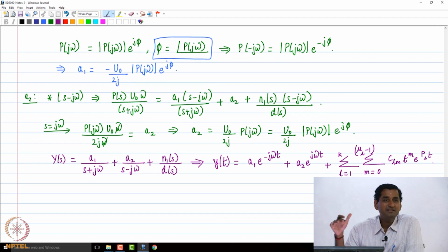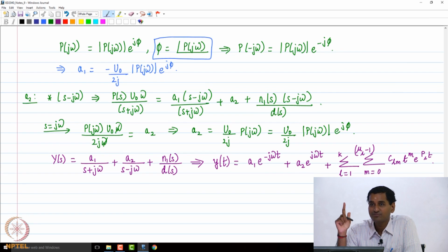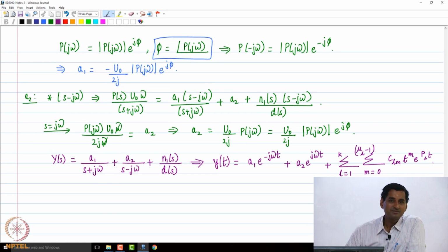The main thing is that we are going to have the poles as the exponents. If you recall, we did this when we analyzed stability, and this is the result where we figured out that if my poles lie in the left of the complex plane, the system is going to be BIBO stable. That is what we did some classes back. So, essentially I am just going to get the same structure. That is very important as far as this is concerned.